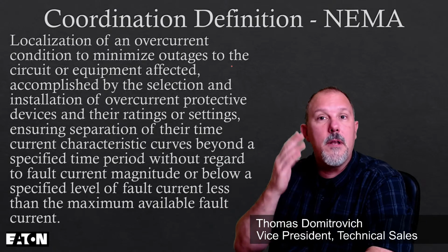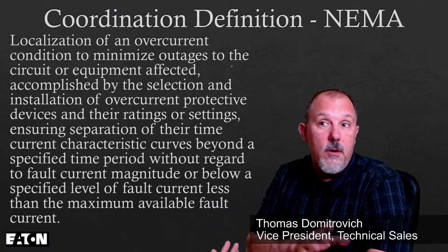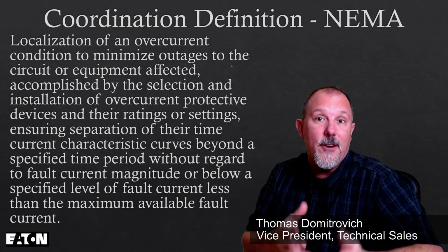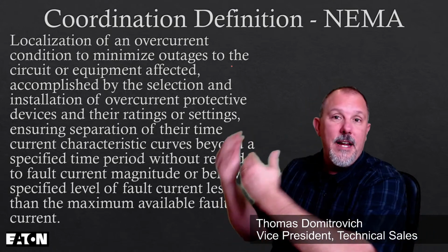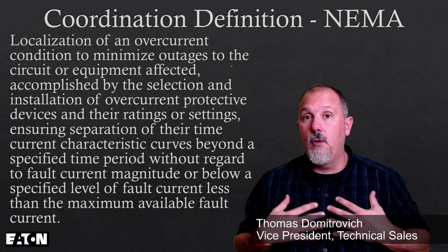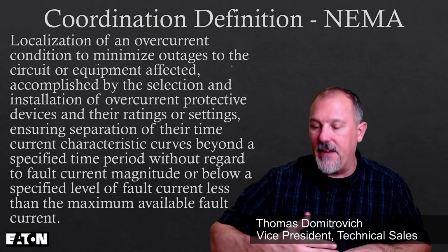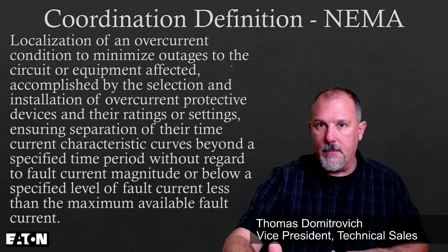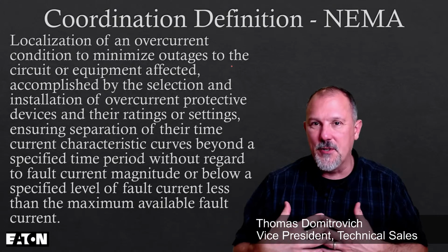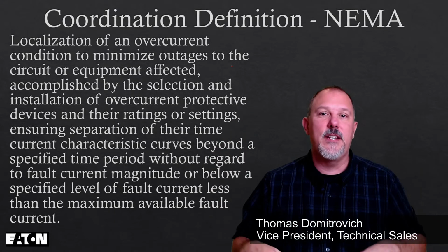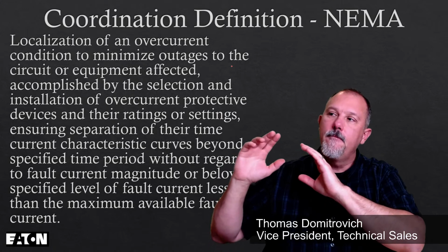And then I would plot that one, and I would either tell the customer, look, you don't selectively coordinate, but you coordinate to this arcing fault current value, which is based on IEEE 242, because I would never pull numbers out of my butt on my own. I would always reference an IEEE. If I had an IEEE document that I can reference, that would be the value proposition for me, as a professional engineer, to say, look, this isn't Tom and his 20 years experience. This is IEEE